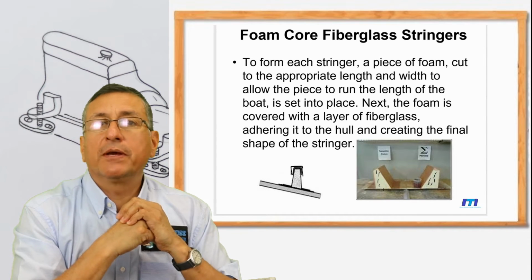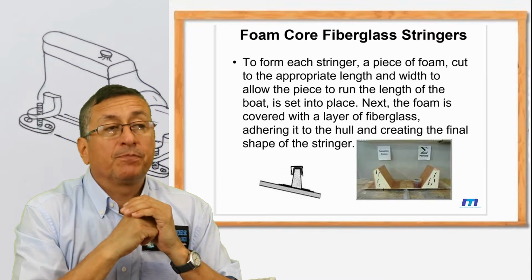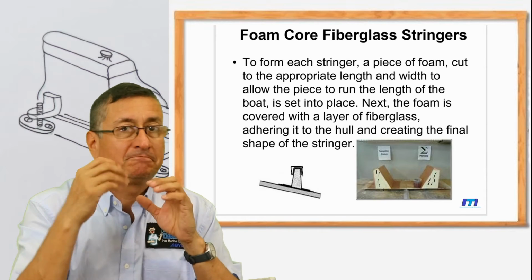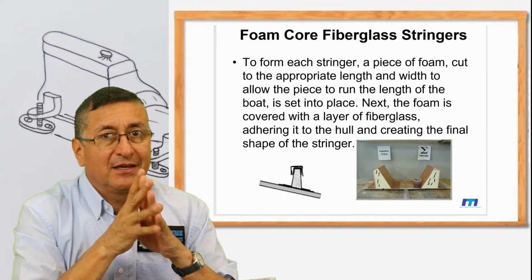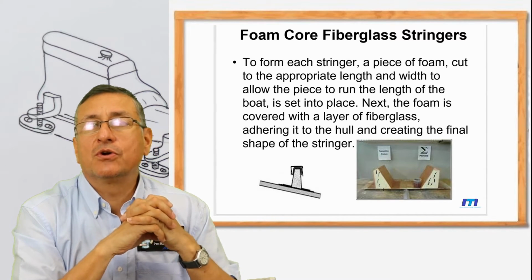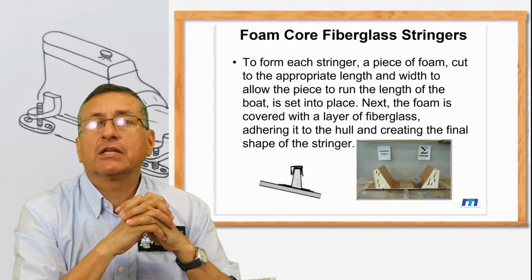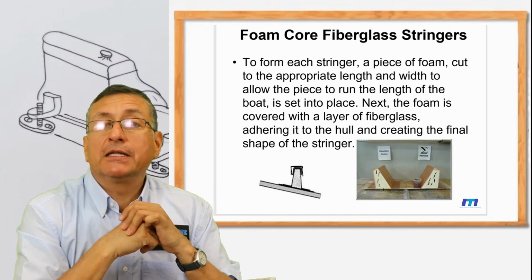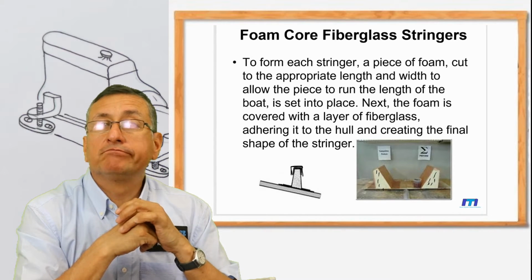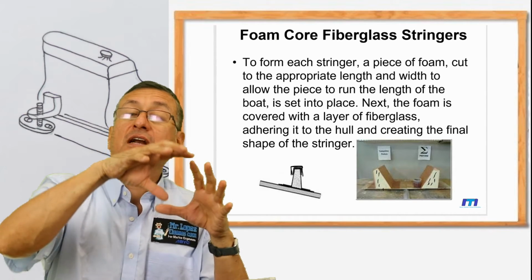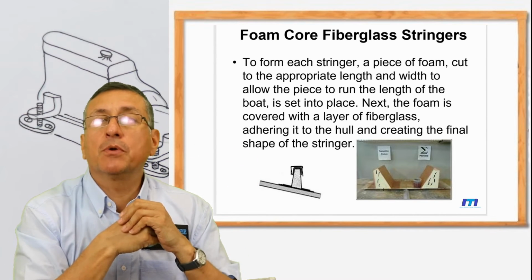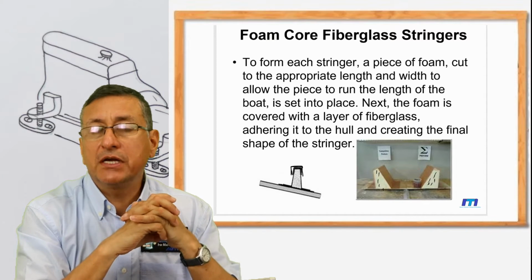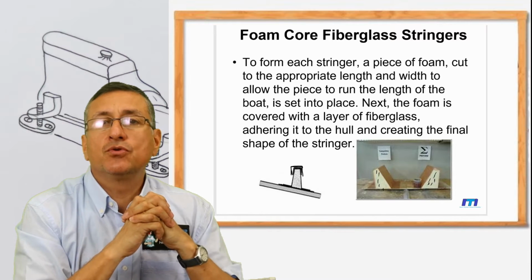The life of the boat depends on the condition of the stringers. Yes, the majority of the boats that you find on the internet for nothing, for free, are there because the stringers or the transom are broken. For that reason, the boat is out. Once again, yes, it's possible to repair, but in some cases the repair is more expensive than buying a new boat. For that reason, be careful with the condition of the stringers before you buy a used boat.